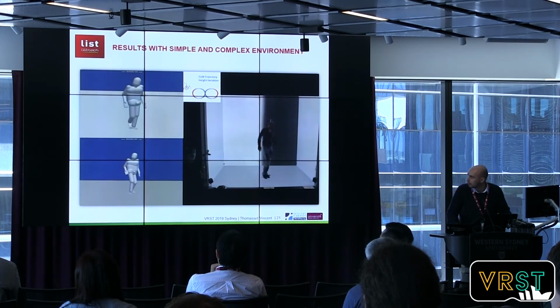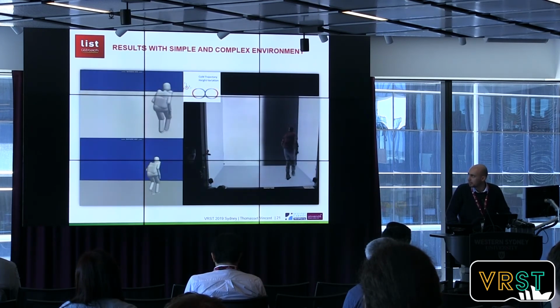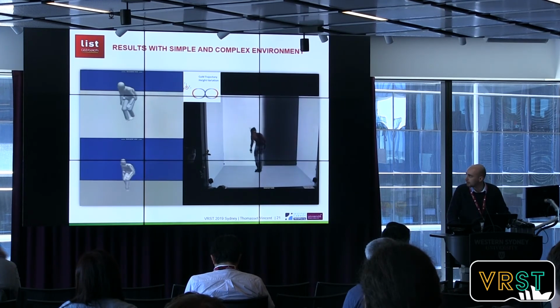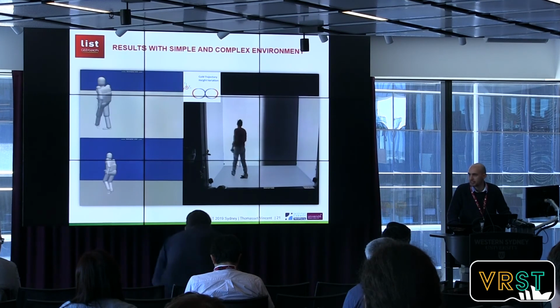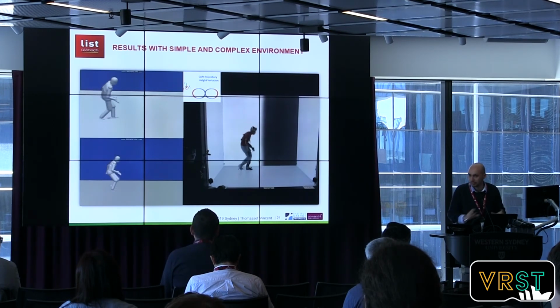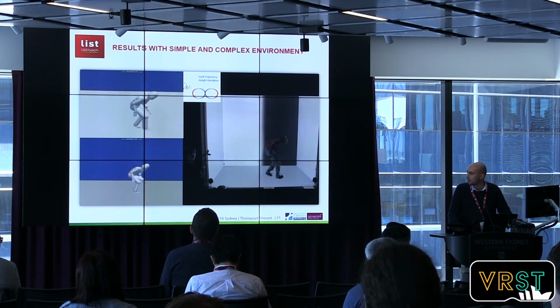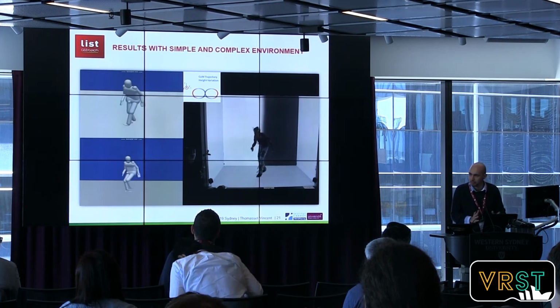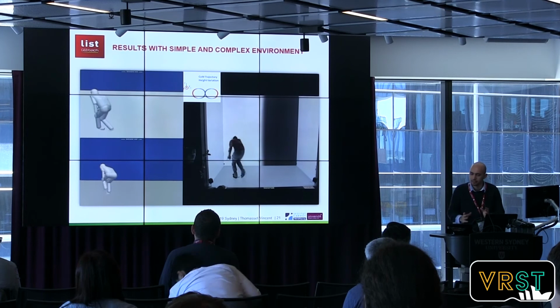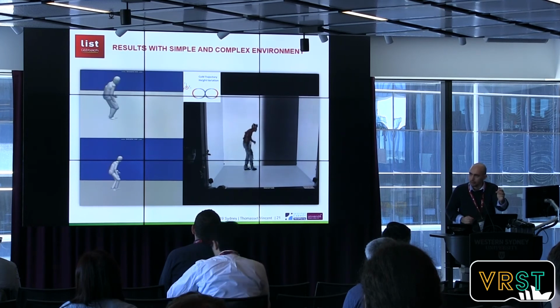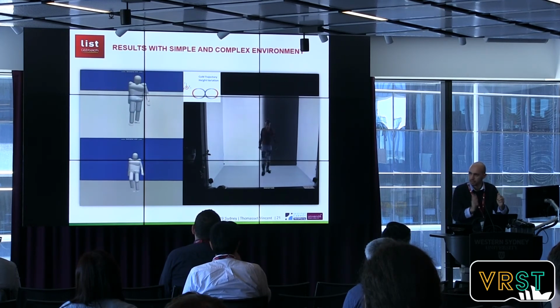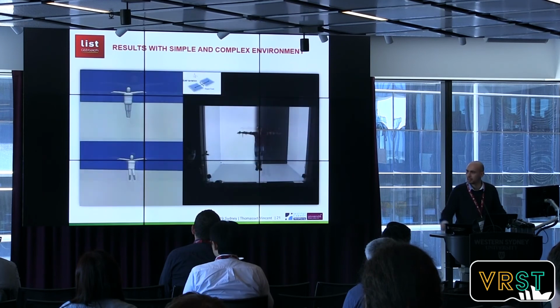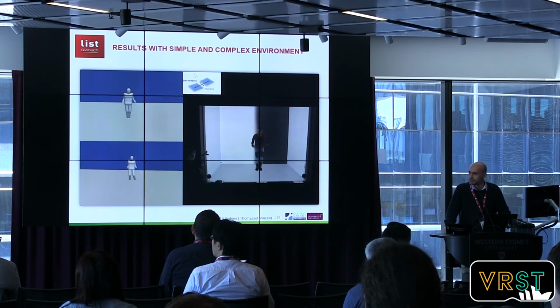Okay, we can maintain sidestep walking with this model. Yes, it's part of the solution, but in that kind of application, the step may be smaller because the support area is wider on the x-axis for walking forward, and not on the wide. Thank you for your question.